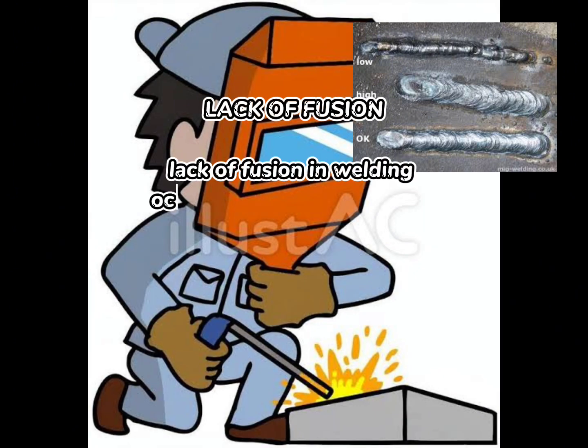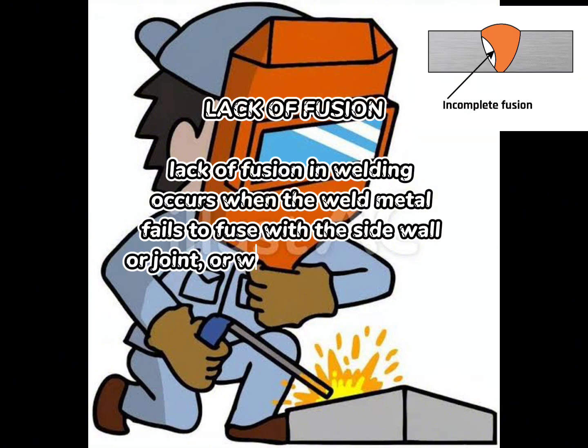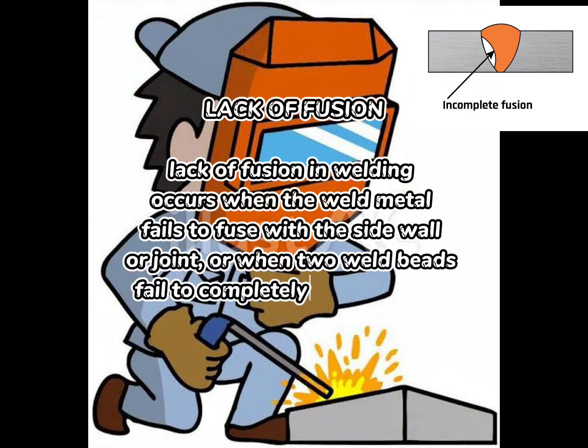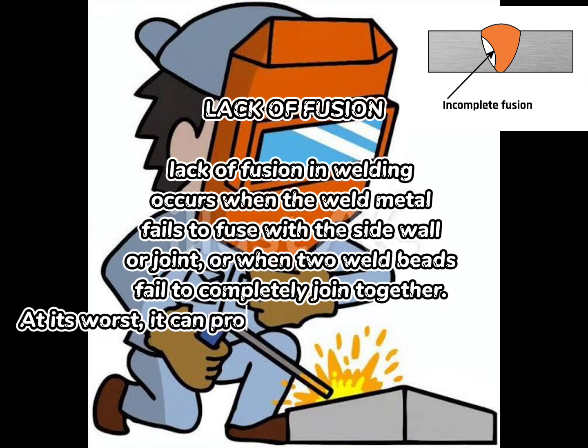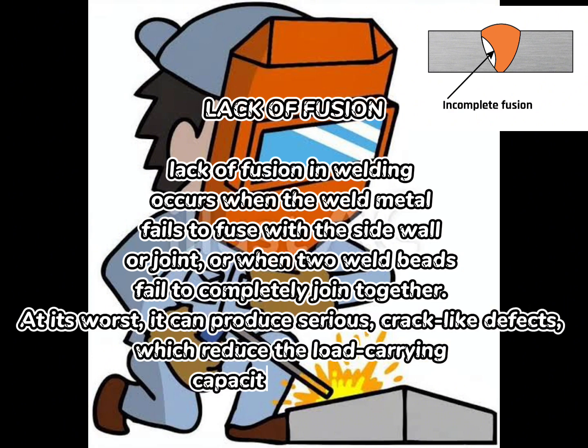Lack of fusion. Lack of fusion in welding occurs when the weld metal fails to fuse with the sidewall or joint, or when two weld beads fail to completely join together. At its worst, it can produce serious crack-like defects, which reduce the load-carrying capacity of the joint.